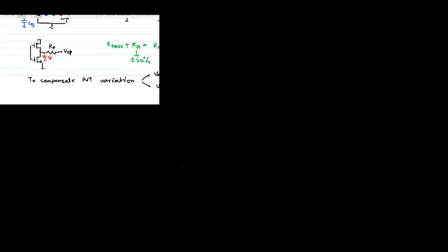So let's say your RT resistance is equal to some n. The way to vary the resistance is to use a number of segments and use only a selected number of segments depending on the PVT variation. So RT is equal to, let's say, R MOS 0, which is the R MOS cell, plus R poly 0, divided by n. That means at a time I can use n segments and get the desired termination resistance.